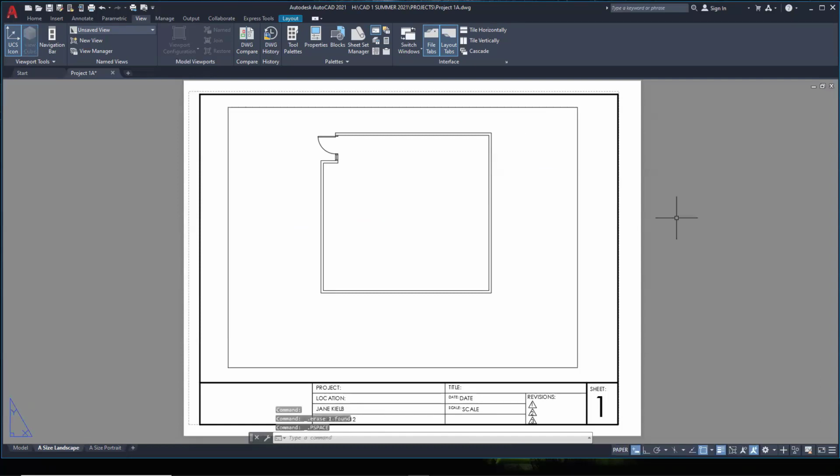How do I know I'm in paper space? Well, that UCS icon has disappeared here. And you'll notice in the lower left-hand corner, the model space icon has appeared here. Also, and you may have noticed this before, and we haven't talked about it, but there is a little button here that says paper. And that tells me that I am in paper space. If I click on this,